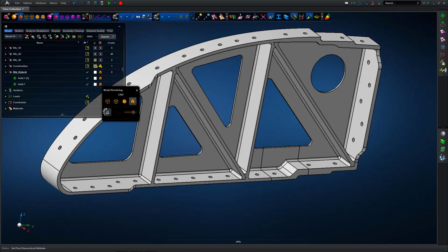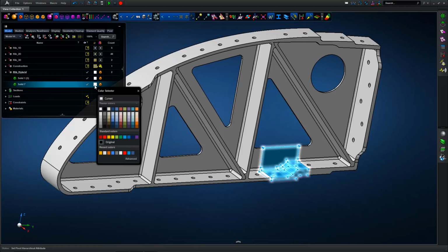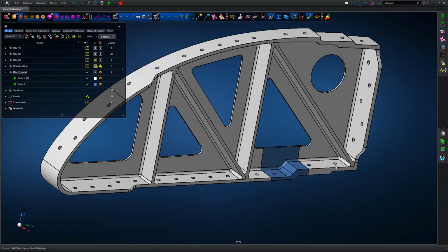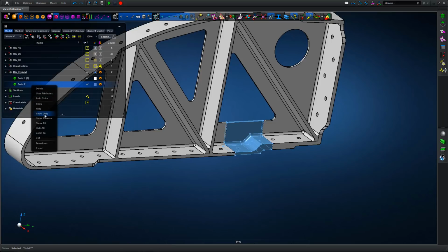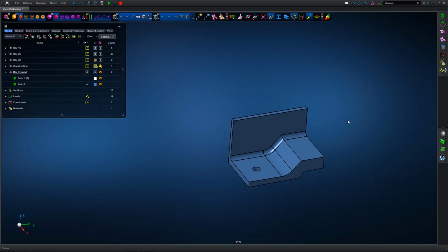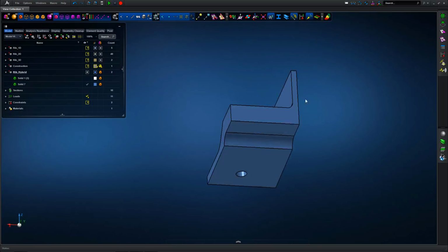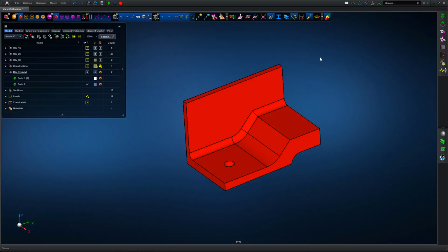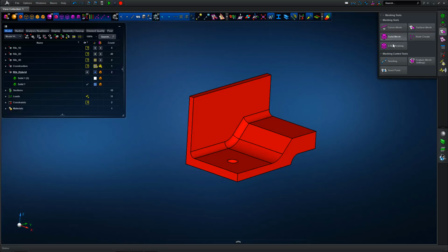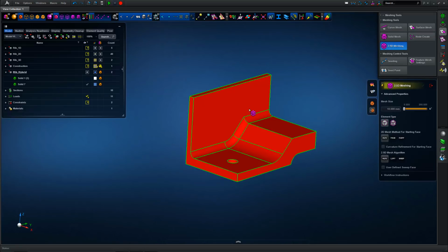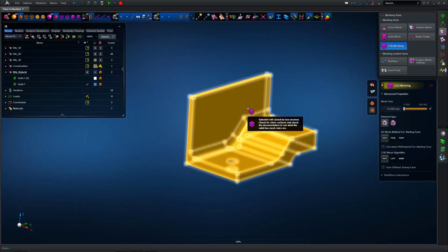So just in the model browser tree, changing the colour of the new part that's been cut out of the original rib, I should say. So you can see we've now got two parts in the model browser tree. So focused on this particular region, we're going to highlight some of the hexahedral or hex mesh techniques. So this is all based on mappable geometry.